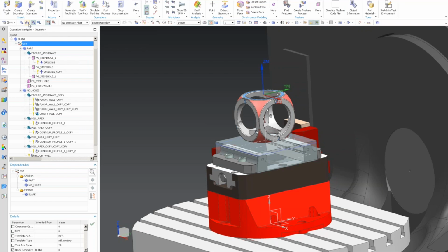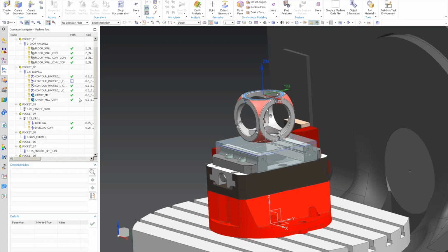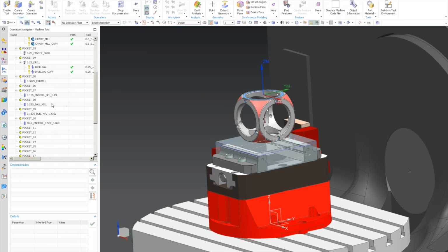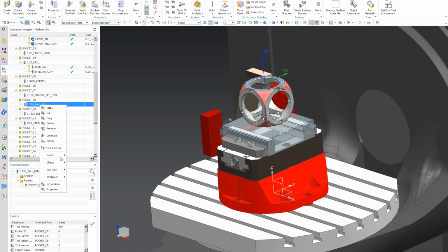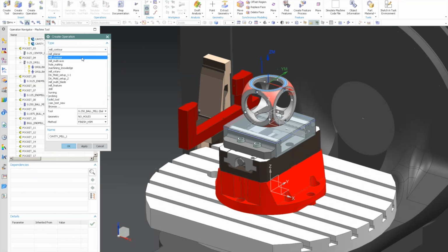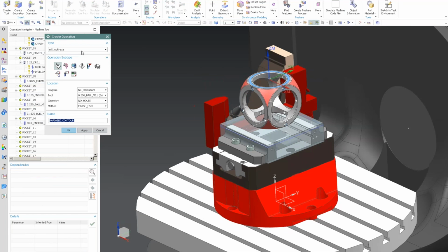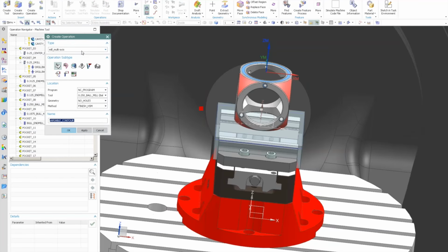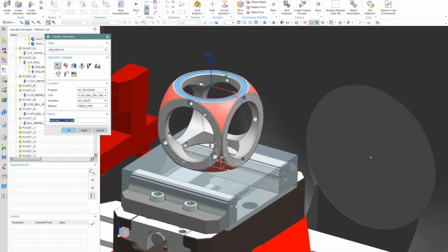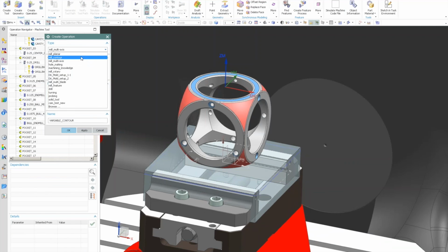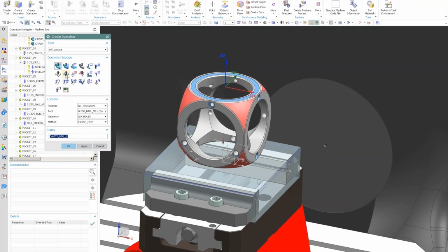It's a good question. Okay, so let's see what we have for tools. A 1/4-inch ball mill. There are a couple of different ways on our multi-axis. Actually, this doesn't even have to be multi-axis. I would probably do it fixed. It runs quicker, and I could just angle to that. So I'll show what I would do.